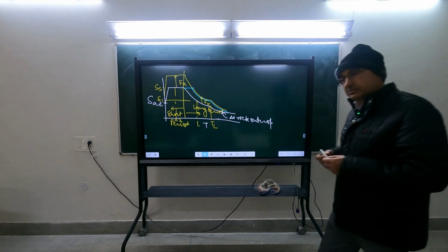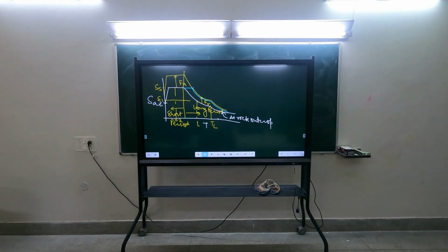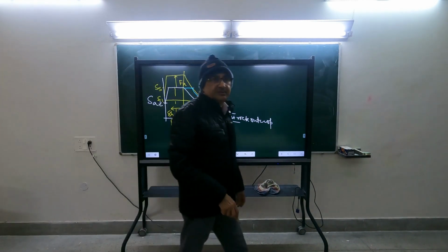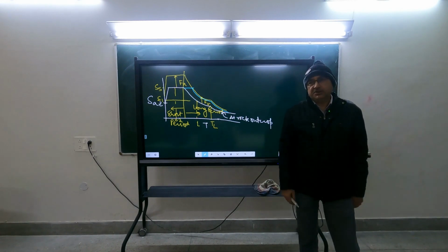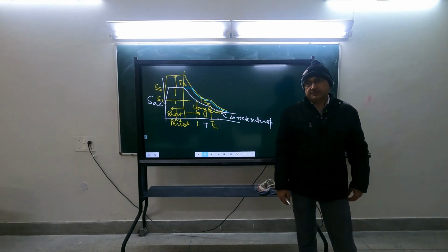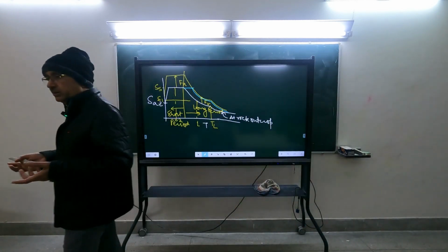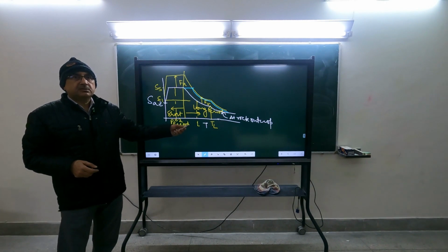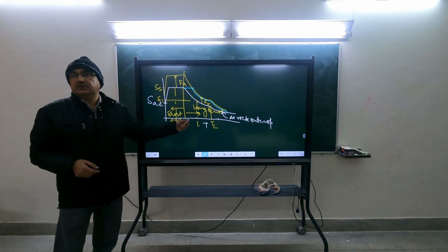Instead of ignoring that part, they could have simply considered that for short period. Yeah, they could have done many things, but they have done it like this. It's not that they do not know that ASCE 7 is doing this. They know. Still, this is what the committee has decided. And their argument is that the period elongates in case of soil, and the site period is not in this range, the site period is usually in this range.